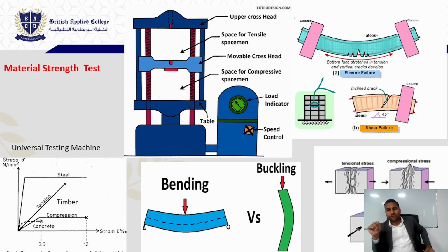Okay, the higher the Young's modulus of elasticity, the higher the strength. That's the basic idea. Young's modulus of elasticity, or modulus of elasticity, is nothing but stress over strain. Stress is force by area, which is Newton per mm square, and strain doesn't have any unit, because strain is change in length by original length, so the units cancel out each other.